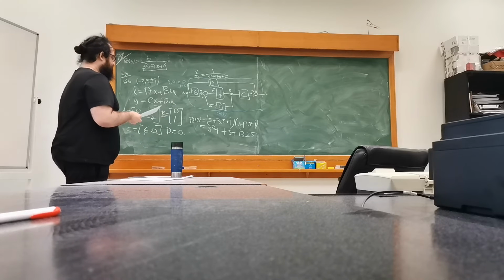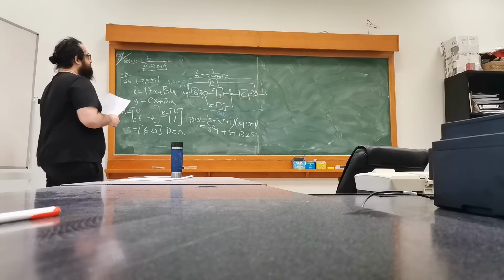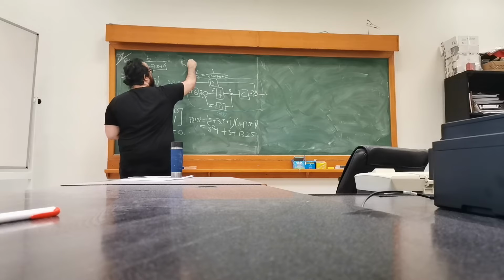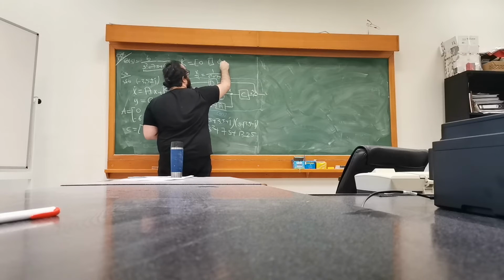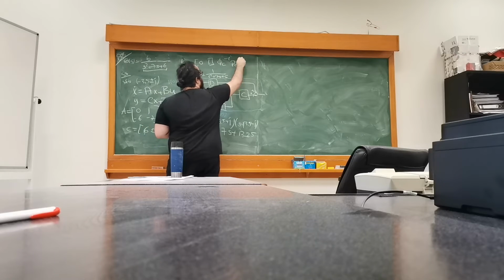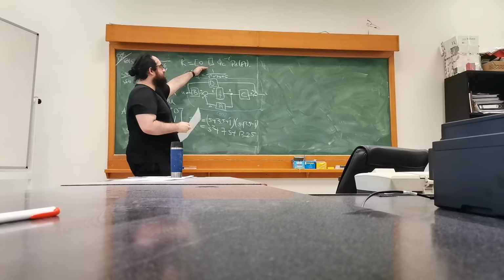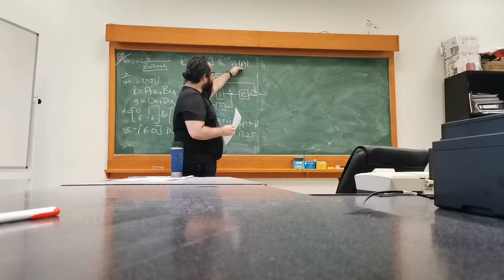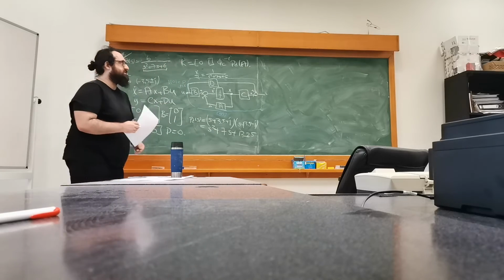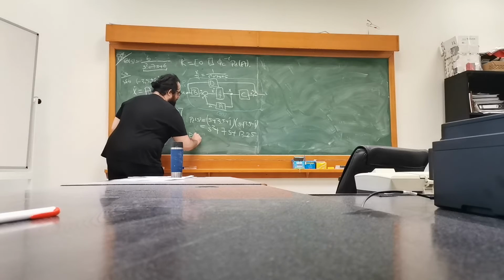Now, this is PD(s), and I've written this for a reason. It's not random, because for designing a state feedback controller, we need to evaluate the Ackermann formula, which uses basically a vector 0, 1, since this is a 2x2 system, the controllability matrix inverse, and a certain PD(s) at s equals A. So therefore, first we need to evaluate what PD(A) is.